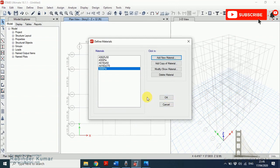If you want to add different materials, because in general practice we assign different types of concrete in a structure. For example, for columns we sometimes use 4000 psi, for slabs 3000 psi, and for beams 4000 psi. In this way you can define different types of materials or different properties of the same material in this model. So click OK.